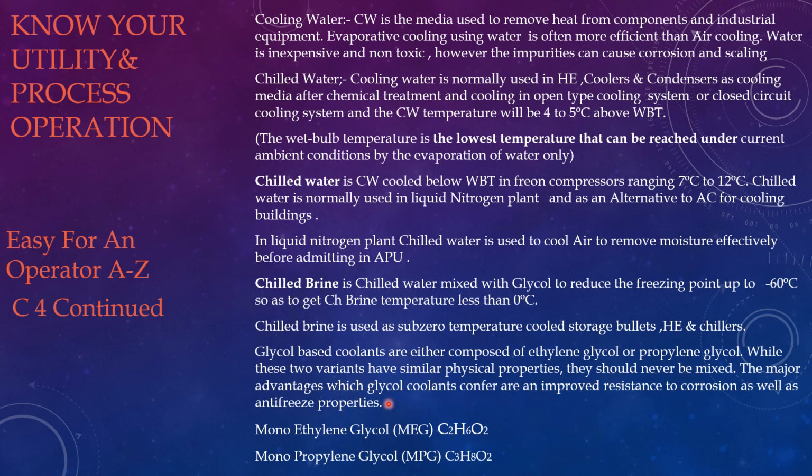The major advantages glycol coolants confer are improved resistance to corrosion as well as antifreeze properties. Whether it is monoethylene glycol or monopropylene glycol, based on the requirement you can mix it with DM water or raw water. In an LNG regasification plant, DM water is used for more purity. The coolant MEG is used in some plants.